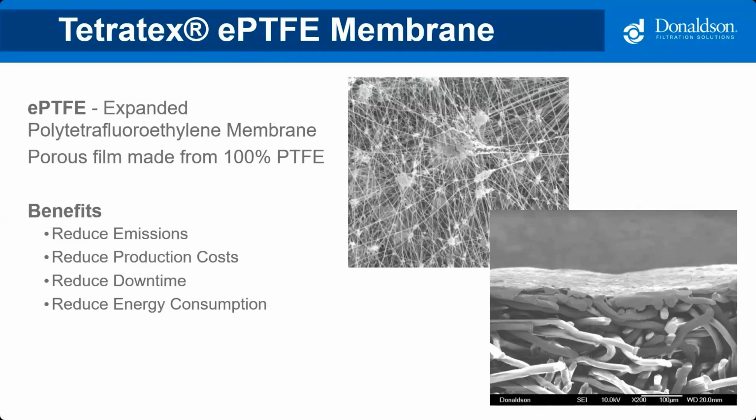Now, in the foundry industry, I'd be kind of careful with using ePTFE membrane. Make sure you're talking to your rep about the actual process, because the Achilles heel of membrane is oil. If you are using it off of your furnaces or off of your molding departments where you might have some binders or some oils coming from dirty steel that you're melting, you could run into some issues using an ePTFE membrane.